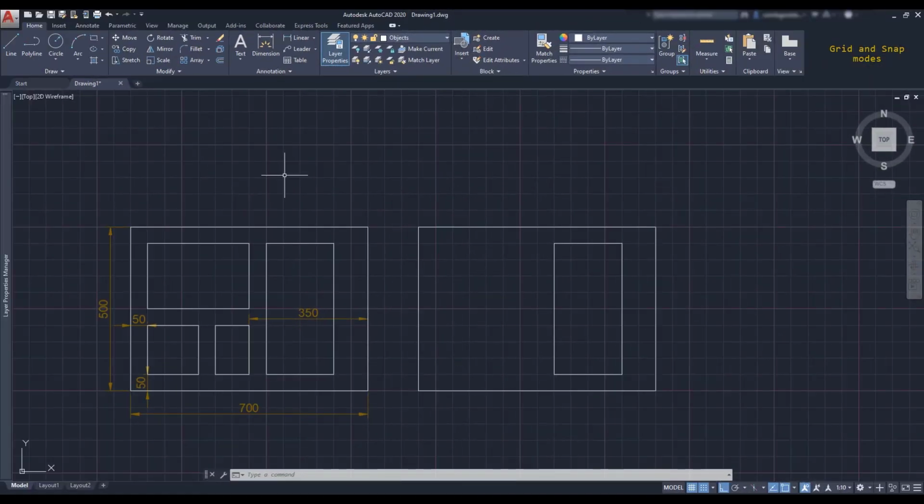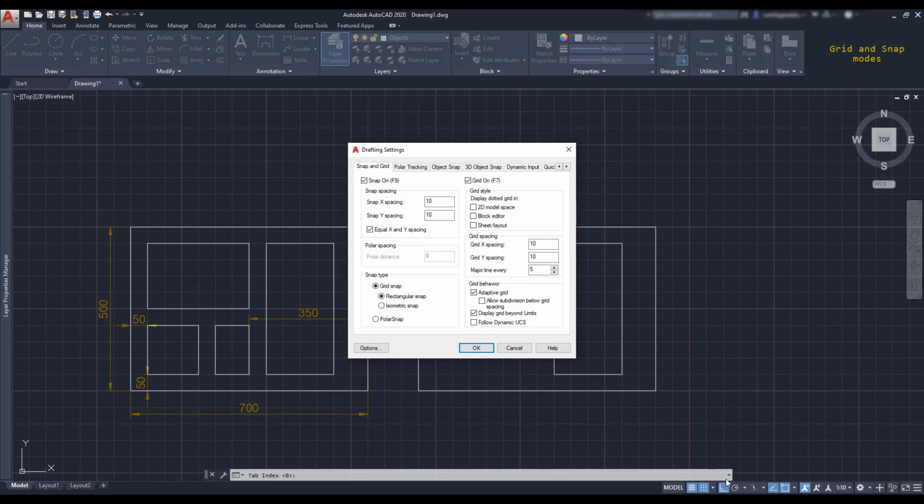Okay, now let's learn to edit the snap and grid spacing. Click on Snap Settings to modify those values. It's in the first tab of the drawing settings window here. Of course, to snap only in every point of the grid, the snap spacing and grid spacing must match. Don't forget this. And the values that I have now are the settings that I used in the previous example.